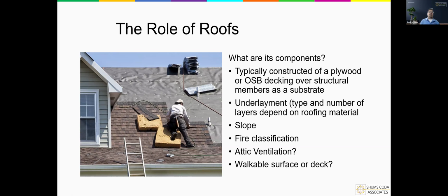I'm not going to get into too much detail, but there are certain roof types, like wood cedar shake, for instance, which is still allowed in large swaths of Colorado, sometimes even preferred by certain HOAs, and it's a requirement to use a roof type like that or something with a similar architectural feature. In those areas, those roofs were designed in such a way as they had significantly more breathing than what we see on an OSB and otherwise completely felted-in roof. These were done with multiple layers of woven-in felt over typically a spaced decking, or spaced sheathing method. That way there was a little bit of gap there, and there was basically airflow underneath those different layers of wood shake.